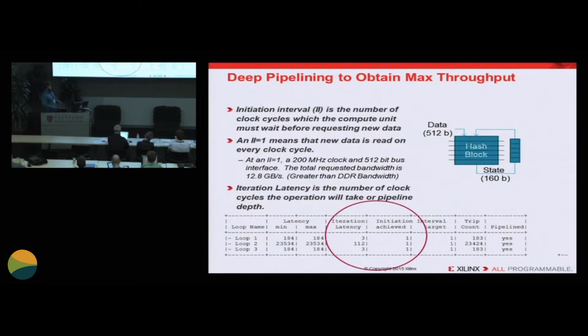So the major goal of this was to see what kind of performance we can get. And performance was really based on the total throughput. So we're doing multiple SHA-1 channels at a given time, a total of 2 times 83, so there's 160 odd channels that are used. And for each channel, it takes 112 clock cycles to go from the data coming in, the state coming in, to a result that is the new state. And you can see here, this is one of our reports.